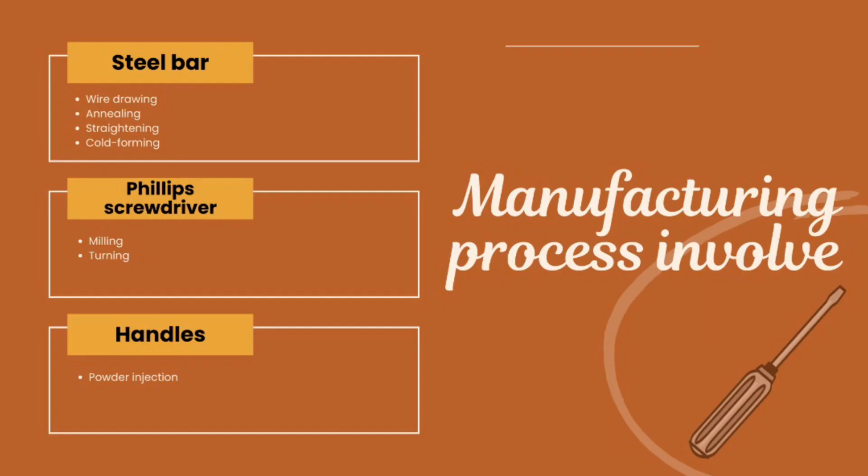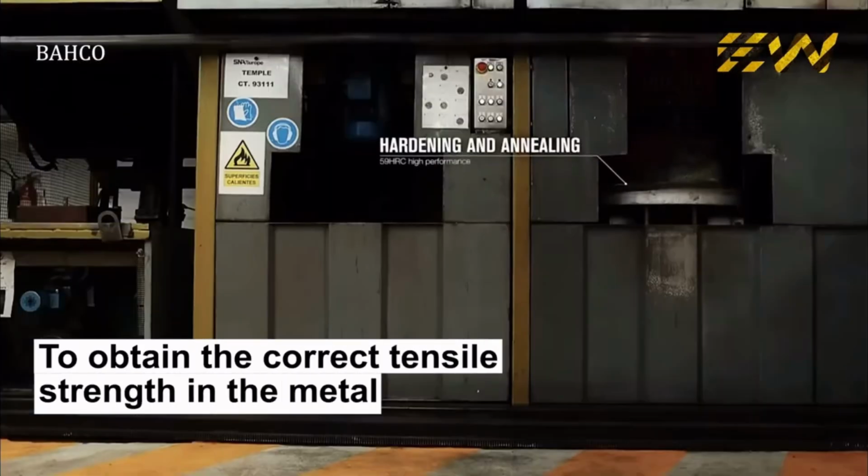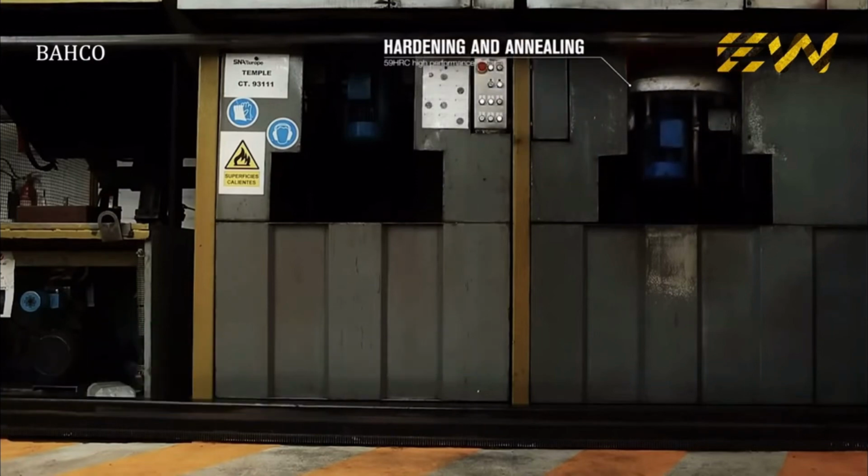After the wire is drawn, the next process is annealing. Annealing is a heat treatment process that changes the physical and sometimes also the chemical properties of a material to increase ductility to make it workable. The process involves baking the wire at a temperature of about 732 degrees Celsius for 12 hours.